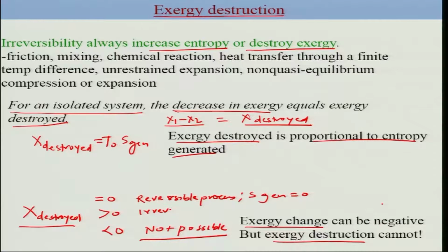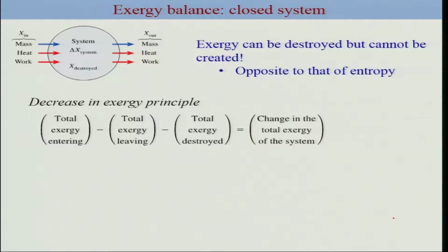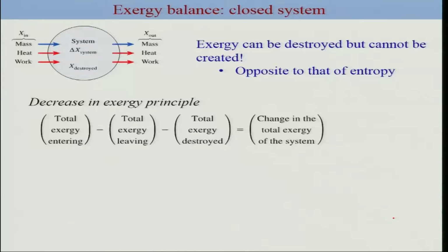as we already discussed. So, now we can extend this understanding and we can apply this exergy balance for the complete system, just as we did such kind of balances for energy and entropy. Now, we are going to extend this concept to exergy. So, what will be the exergy balance? So, this will include the transfer due to heat, mass and work, okay, and then this will also include any exergy which is being destroyed in the process, and that would finally yield a change in the exergy of the system. So, this is a schematic representation of the system.